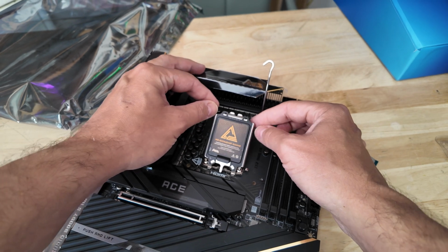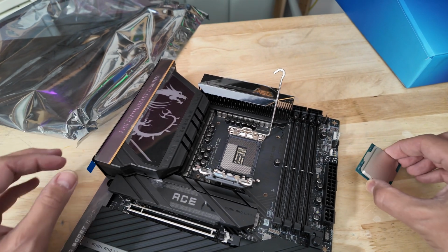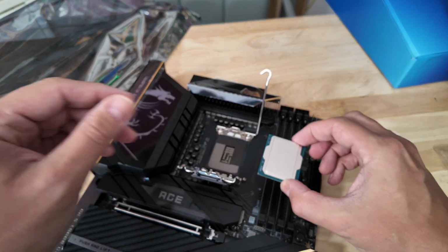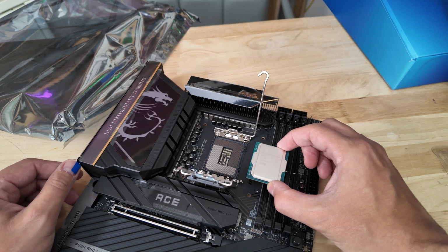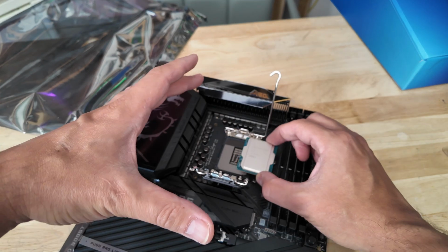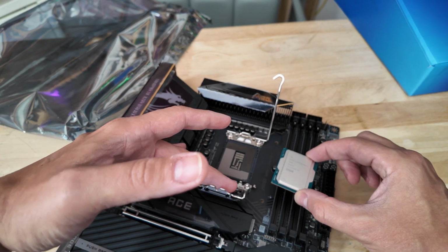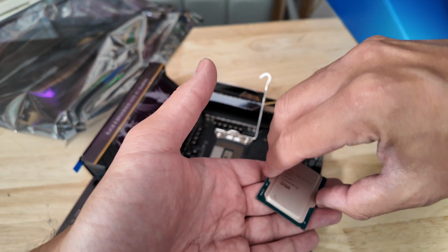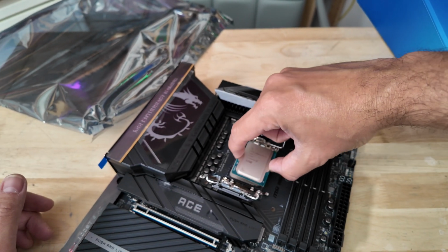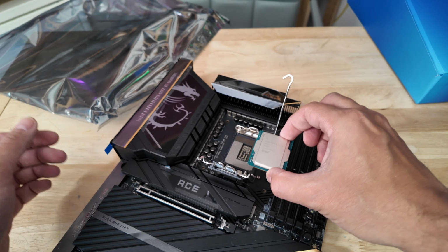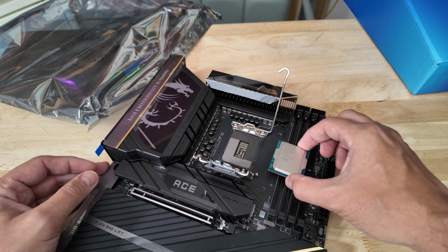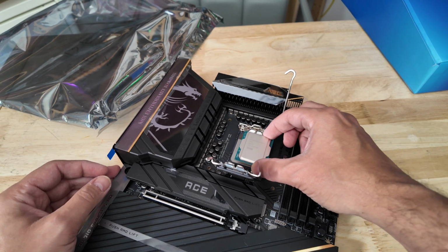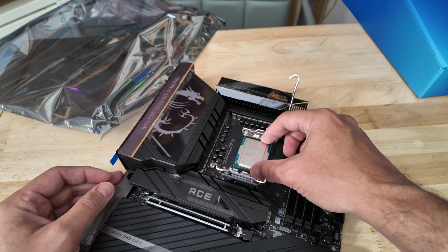So clearly mounting pressure is something of a concern for Intel. So for me, I think I would probably prefer to hold the processor end to end like that. That feels more comfortable to me. I can move my hand into the processor socket from one side. You could probably do it edge to edge as well. That would also work, but I feel like I've got a better grip of it like this. So to move it into the socket, what I tend to do is just lower it right down so your fingers are pretty much touching the memory slots, move it over, and drop it into place like so.